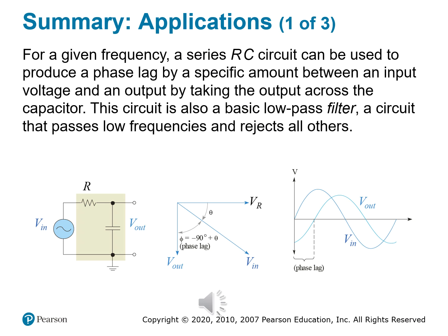So imagine you're trying to delay a signal slightly. Maybe you want to realign it with another, or to simulate a time offset. A series RC circuit can do that. And here's the trick. You apply an AC voltage to the input and then measure the output across the capacitor. Remember, where you measure is important. The output doesn't just dip in amplitude, it lags behind the input.